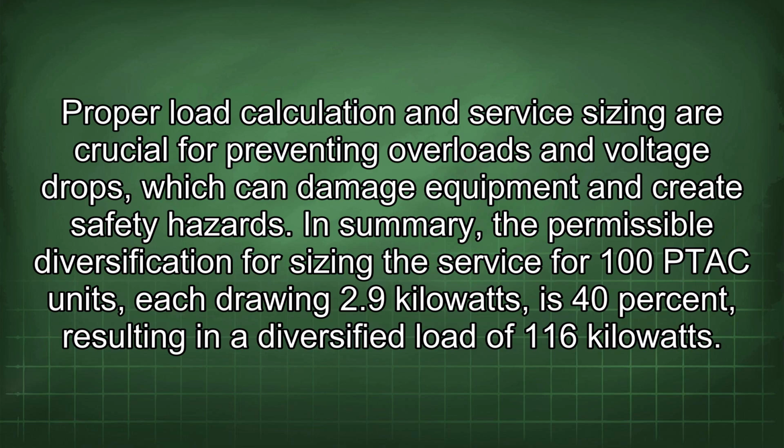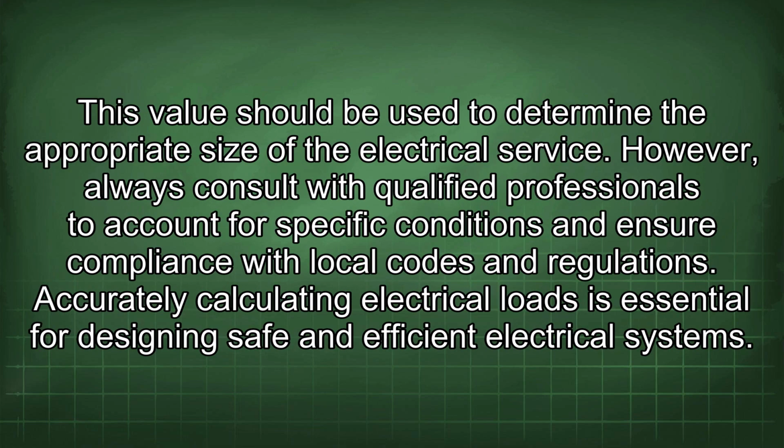In summary, the permissible diversification for sizing the service for 100 PTAC units, each drawing 2.9 kilowatts, is 40%, resulting in a diversified load of 116 kilowatts. This value should be used to determine the appropriate size of the electrical service. However, always consult with qualified professionals to account for specific conditions and ensure compliance with local codes and regulations.